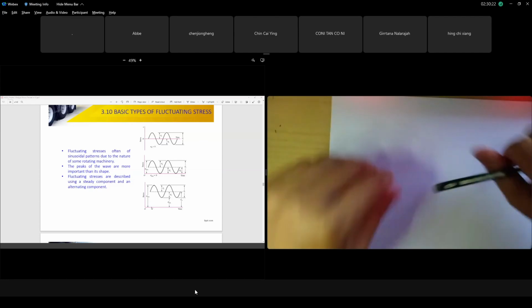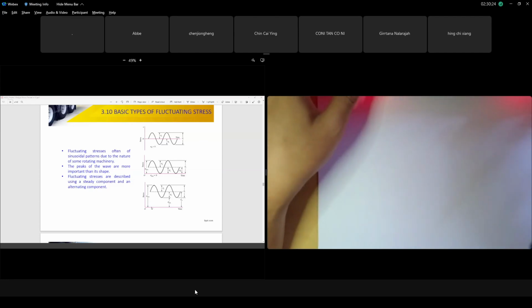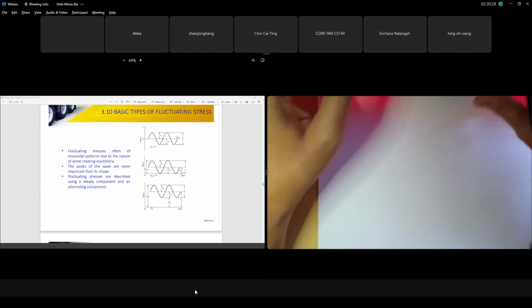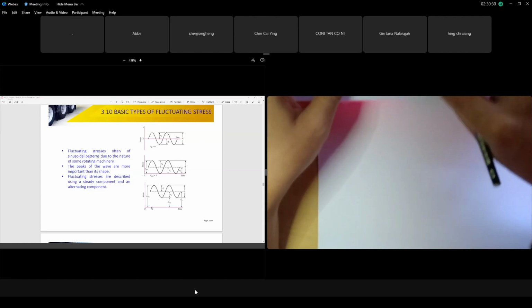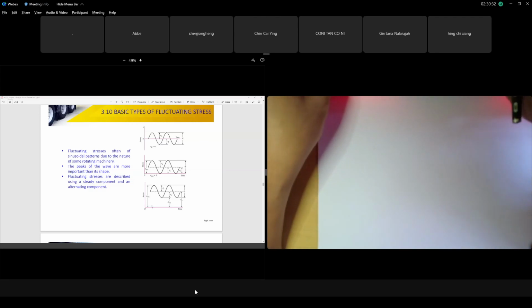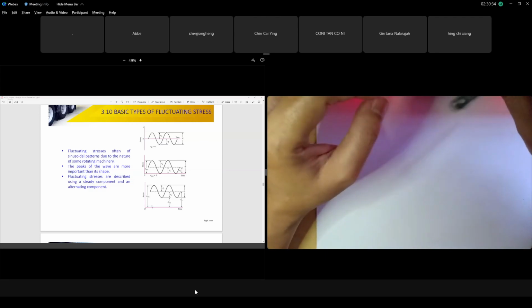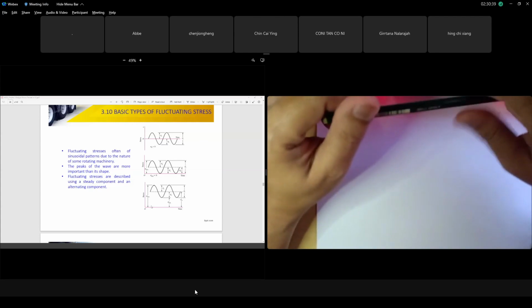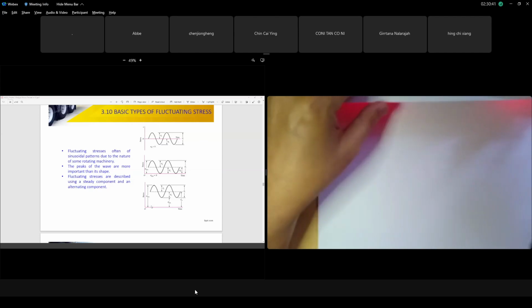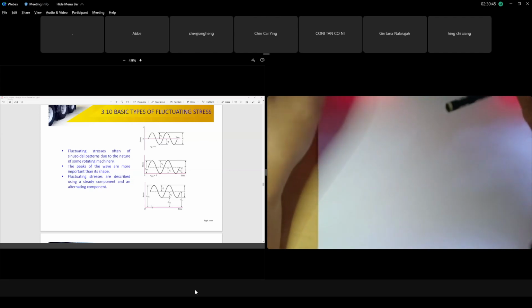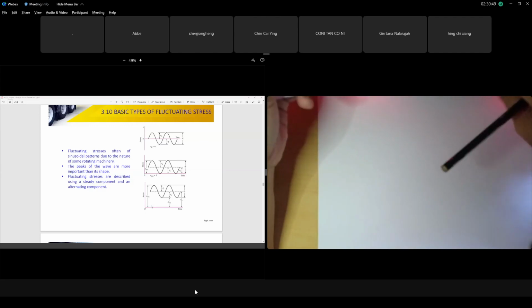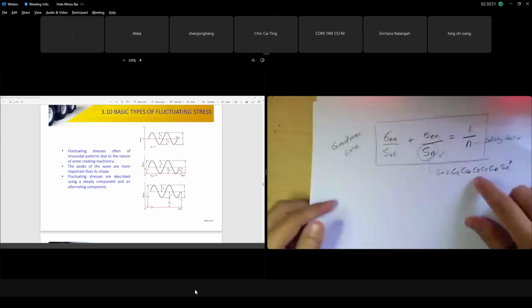Okay, then that's why. I haven't covered everything; next time I will explain the fatigue stress concentration factor, because when you have a hole there is stress concentration. But before that, our stress, the equivalent stress that we calculate, must be multiplied by the KF. Later I will explain to you about KF next time. But my point is, remember what I told you earlier about the equation for the safety factor. What is it? The main equation.